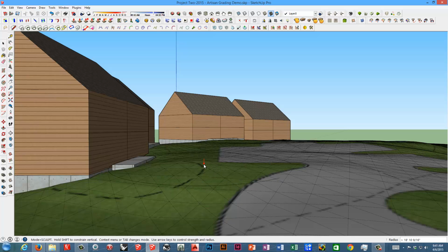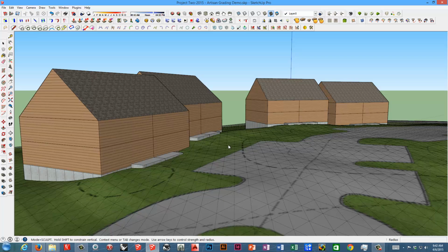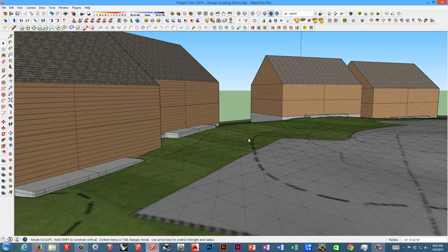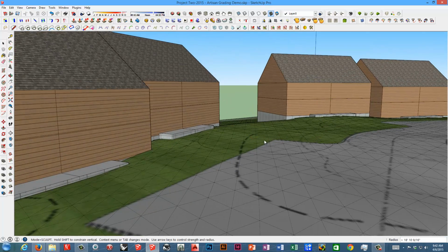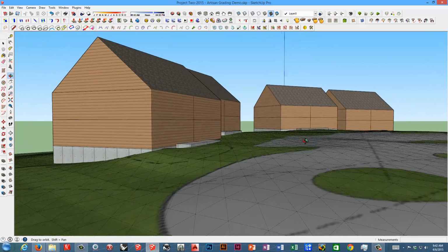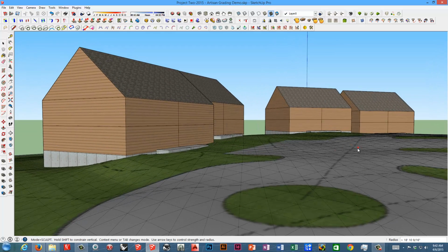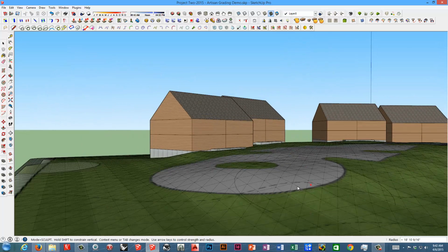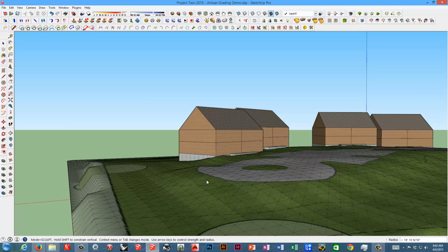And all the time trying to make sure that it looks like it's draining down away from the building. It starts getting too big or too high, and then it's not going to work. So I'm just pulling it up a little bit in there to get that gradient. And maybe back down again. All right, come back around here. So in order to get this up, I'm going to have to come out a little bit beyond the edge of that again, and maybe make my influence a little smaller so it's not going to go down into those trees.